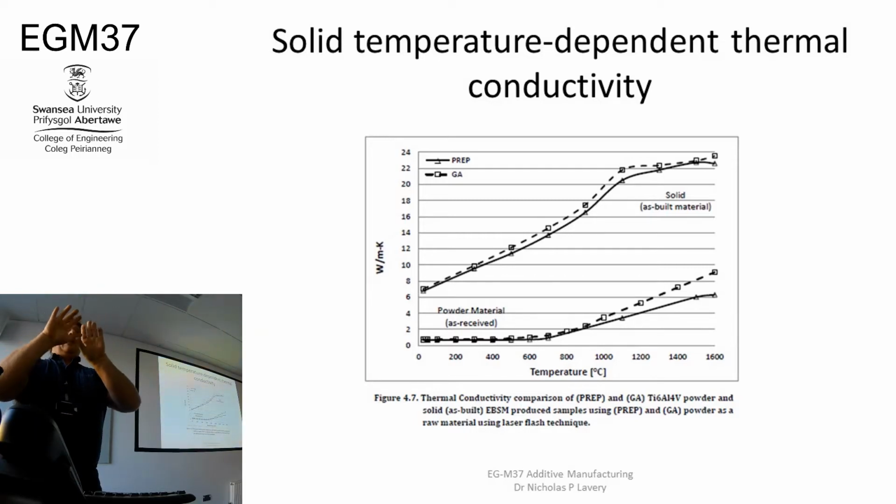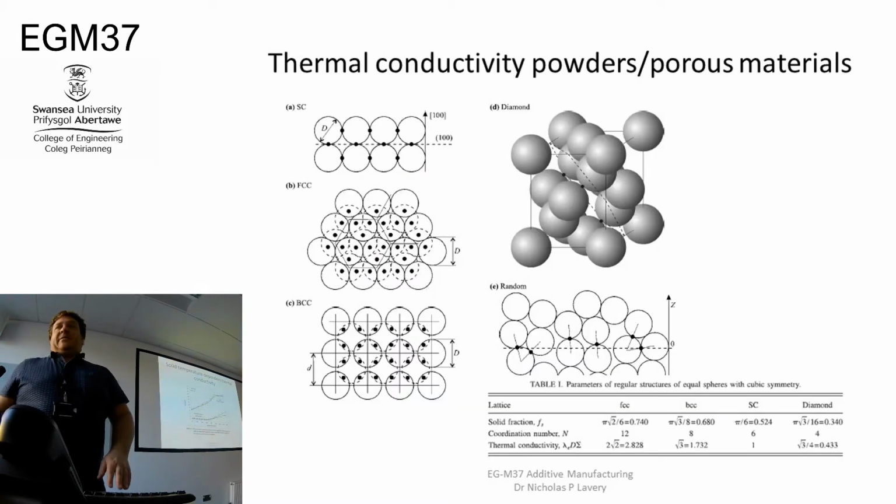Now if you think about it, you've got a powder bed and you've got a component in the middle of it. The heat's not going to want to go through the powder. It's going to go through the component. So the only thing that you've got to get that heat away from the component is the component itself that's been pre-built, and then also maybe some support structures that you put around it. There'll be variation in thermal conductivity of the support structures. There's a variation with temperature of the thermal conductivity of the part as it goes down towards the plate. But that will determine that connection, if you like, with the grain structure as it goes through. So the conductivity itself, how much heat it can whip away, determines the absolute magnitude of the cooling rates, and therefore also affects the microstructure.